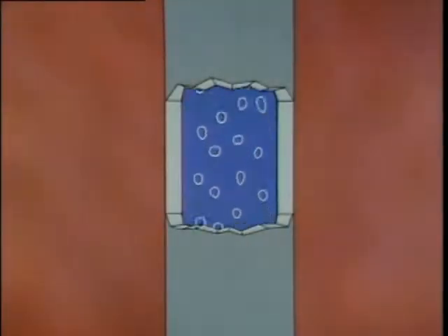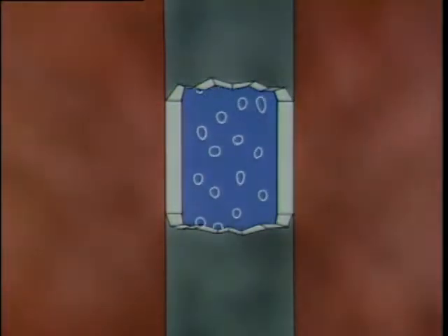In boilers that burn coal or oil, another problem that can affect heat transfer is the buildup of soot. Soot is created by ash and unburned fuel particles in the combustion gases. Soot buildup insulates the surfaces, preventing good heat transfer. When this occurs, the amount of heat transfer to the water decreases. As a result, heat is wasted. It escapes with the gases routed out of the boiler, reducing boiler efficiency.